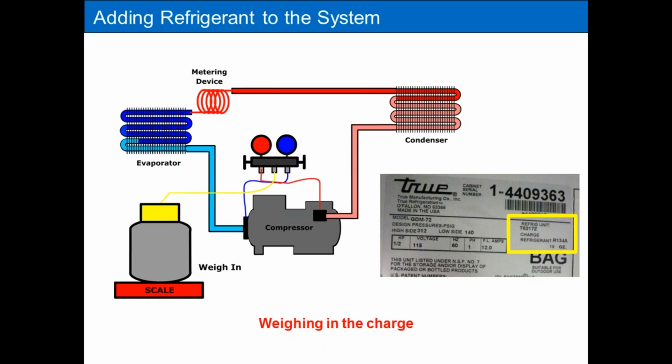When it comes to adding refrigerant back into these units, best practice is weighing in the charge. Weigh in whatever the manufacturer told you the original charge should be. Forget about the superheat and subcooling approaches. It's very difficult to pinpoint those on these units. If it holds 8 ounces, 9 ounces, or 20 ounces, weigh that in and be done with it. Fix the leak, pressurize it, evacuate it, weigh in the charge, done. Best approach when it comes to these types of systems.